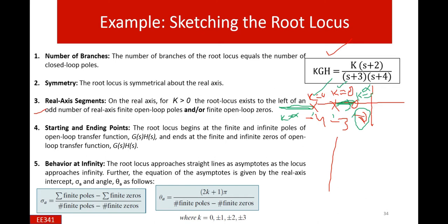So there are two root locus lines. One starts from the -3 pole and ends at -2, and the other starts from the -4 position of the open loop pole and goes to infinity. And there is no need to find the centroid, and this concept will be understood in the next lecture.